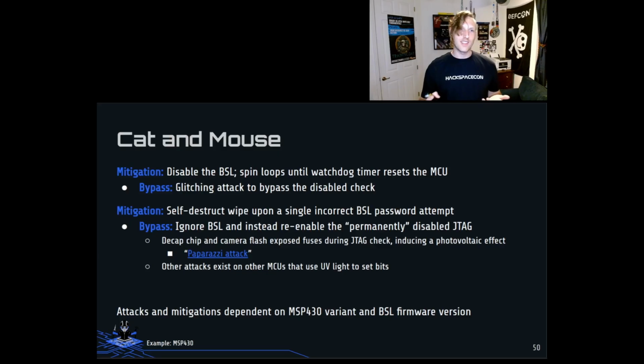And that sounds great, except then now you have a great glitching target that's just constantly checking and then jumping and then checking and jumping. And now you have a ton of targets to try to glitch that jump and fall through and bypass that issue and drop back into the bootloader, into the bootstrap loader. So that doesn't work.